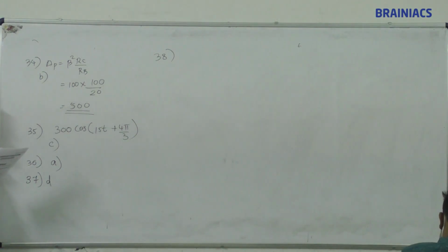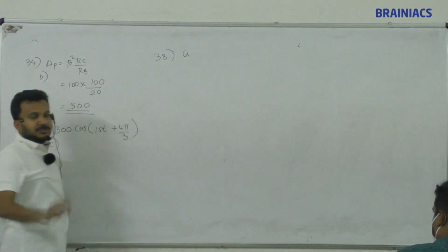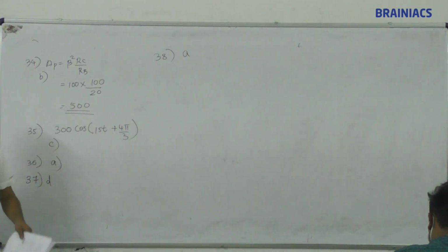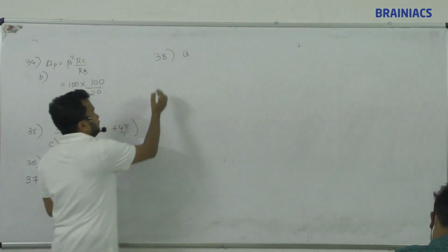Okay, V volt when the diode is forward biased. Same voltage will be available. 38, answer A. It is not 2V, it is V volt, because the diode is forward biased, there is no drop for an ideal diode.